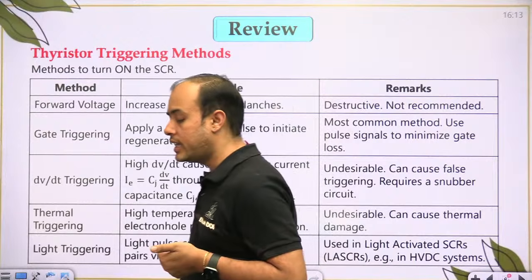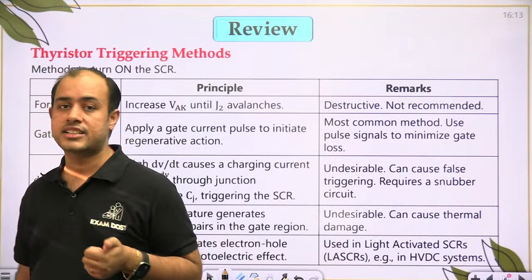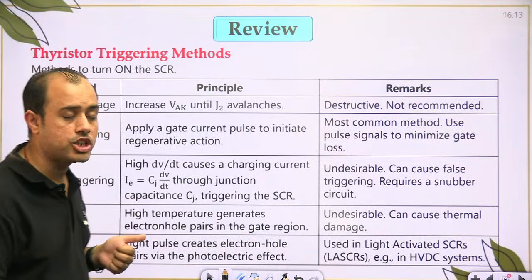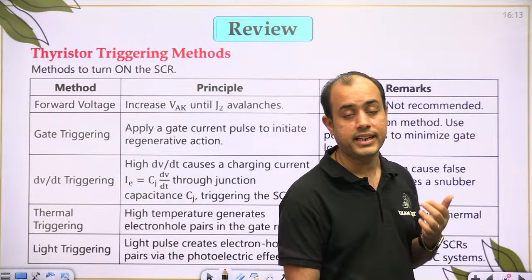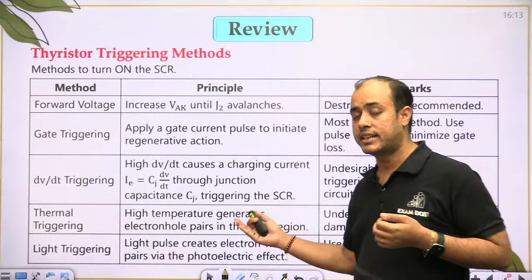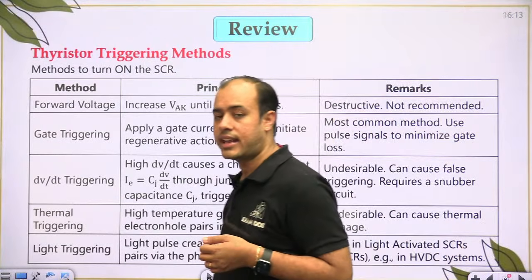In thermal triggering, if you increase the temperature, charge carriers are generated in the gate region. They will act as the gate current and trigger the device. It is undesirable because it can damage the device or change the characteristic.